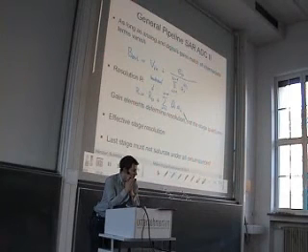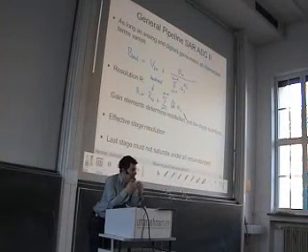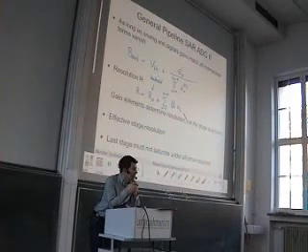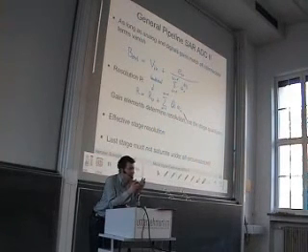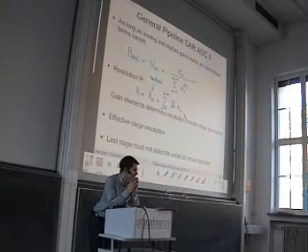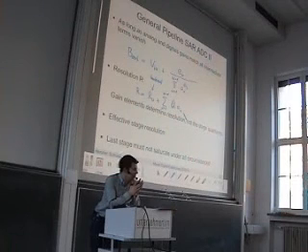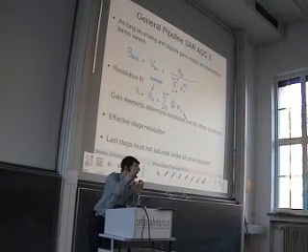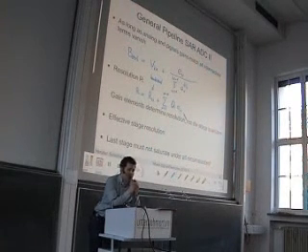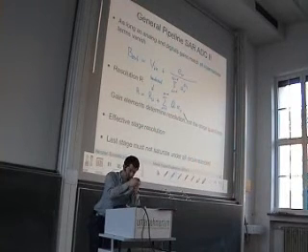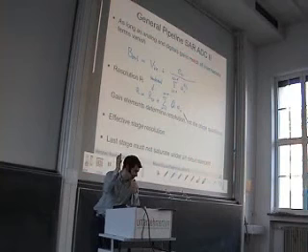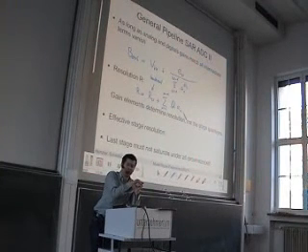Make this clear. So the basic pipeline ADC means we compute in each cycle each bit. Okay, this was what these basic algorithms at the beginning showed. Then we saw this is somehow sensitive to variations. We need redundancy. And the redundancy unfortunately leads to the fact that a certain bit weight comes not out of only one stage, so that we can say, okay, the MSB comes always out of the first stage and the fourth bit comes only from the fourth stage.